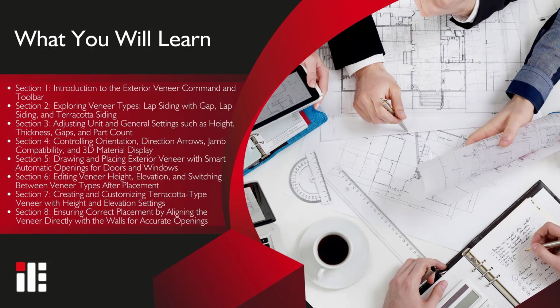In this video, you'll learn how to create exterior veneer in ideCAD. We'll cover different veneer types, including lap siding with a gap, lap siding, and terracotta siding. You'll see how to adjust unit height, thickness, gaps, and orientation, and place veneer that automatically detects doors and windows. We'll also edit veneer properties, switch between types, and ensure correct placement for accurate openings. By the end, you'll know how to design professional exterior veneer systems in ideCAD.